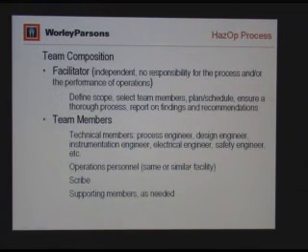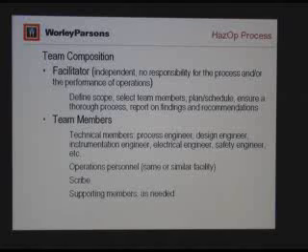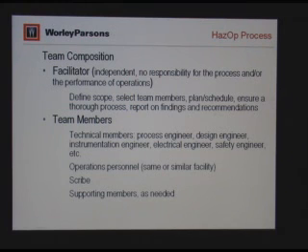And now we're going to talk about who needs to be in HAZOP. First, we need to have a facilitator, and this person needs to be independent. He or she should not be part of the process team who designed the process, and will be the operators on this process.